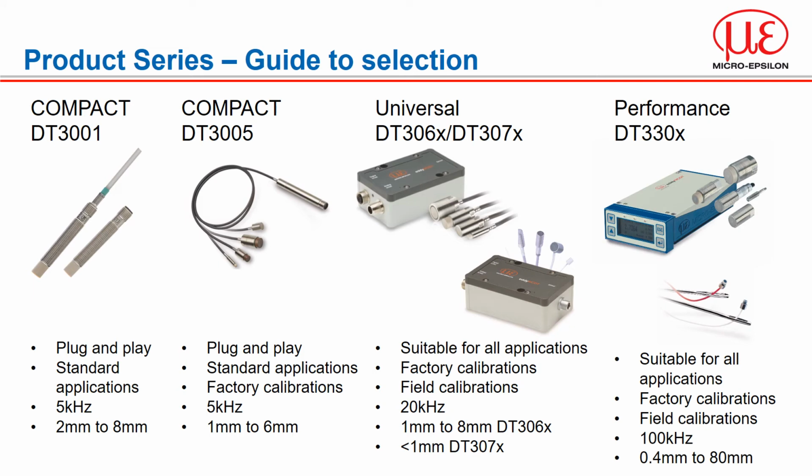Our final controller is the DT3300 series with inbuilt display. Sensors are calibrated to a unique board inside the controller, which can be exchanged to allow for multiple characteristics and cable length changes. This is our fastest controller with frequency response up to 100 kHz for sensor ranges of less than 1 mm, and 25 kHz for all others. It too has limit switches for process control applications.